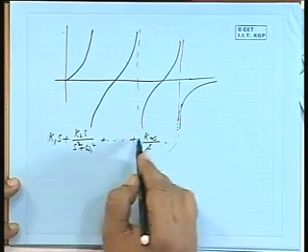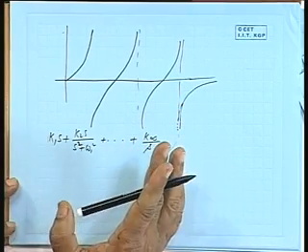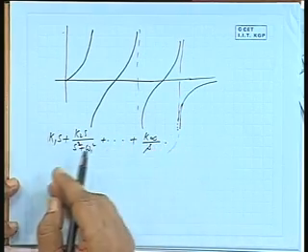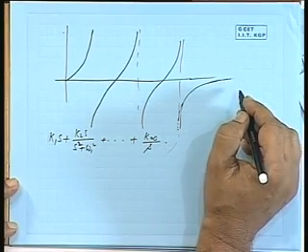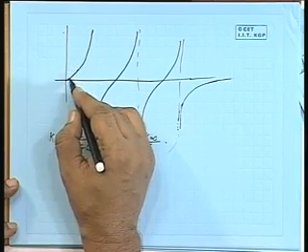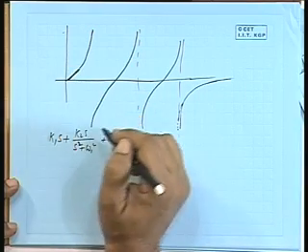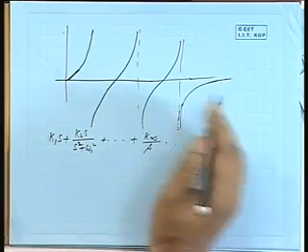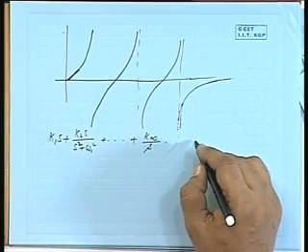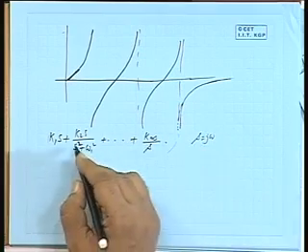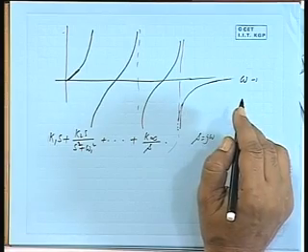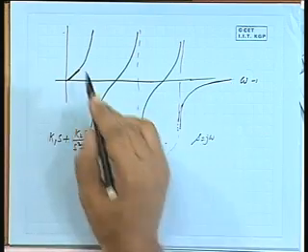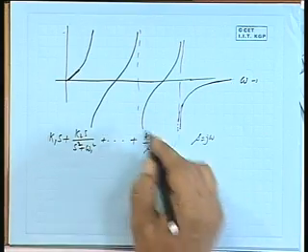So, each one of them you take the derivative and then put s tending to 0 or s tending to infinity, then you will get this slope, or this slope at s equal to 0, alright. So, like that you can find out. We will not make s tending to infinity; s equal to j omega. After taking the derivative we will put s equal to j omega, because this is against omega, and then evaluate the slopes, okay.